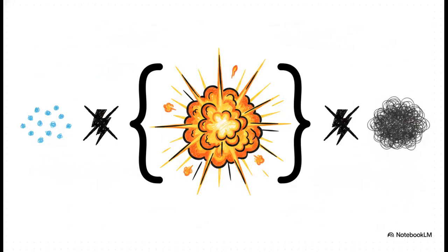So, what does this all mean? The crucial takeaway here is that ignition only propagates within that specific mathematical sweet spot, trapped directly between the LEL and the UEL. Below it, you're safe because it's too lean. Above it, you're technically safe from an immediate spark because it's too rich. The actual danger is entirely confined to that explosive range right in the middle.